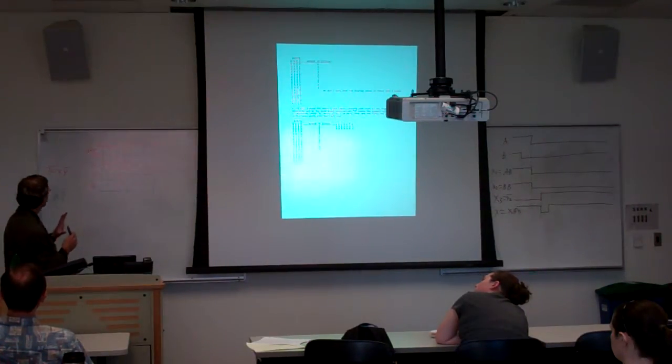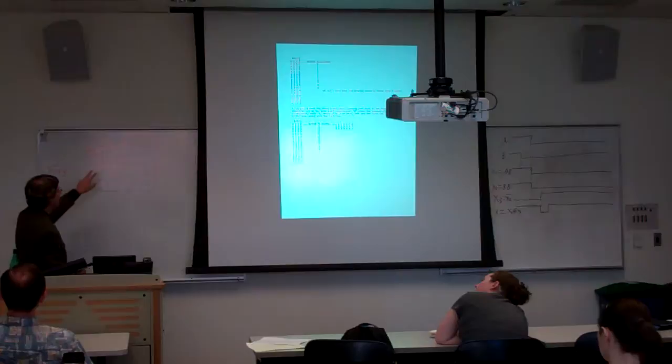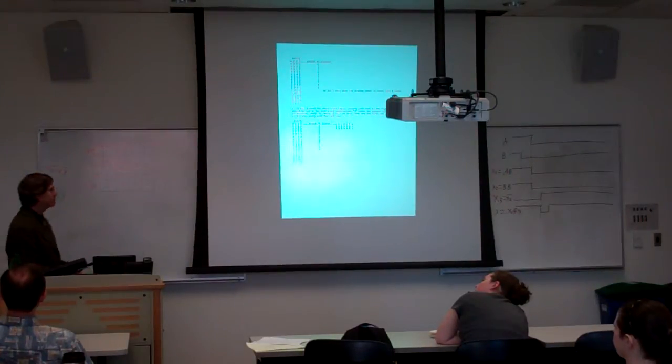So the size of the rectangle corresponds to how many things you have to put in your AND gate. And the number of rectangles, that's how many things you OR together in the end. So if we use big rectangles, we'll get smaller terms, and we'll likely get fewer rectangles that we need also. So you try to cover as much as possible.